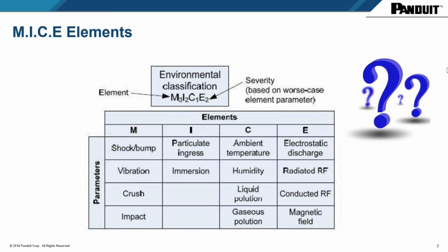There are a lot of chemicals that will attack the plastics and the TPE and all of the different jacketed material that exist on the connector and all of the cable. So you need to be made aware of what type of protection my connector has to withstand, say, in an extreme chemical or caustic environment that it is deployed in.